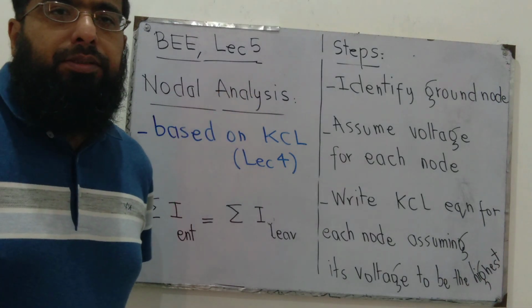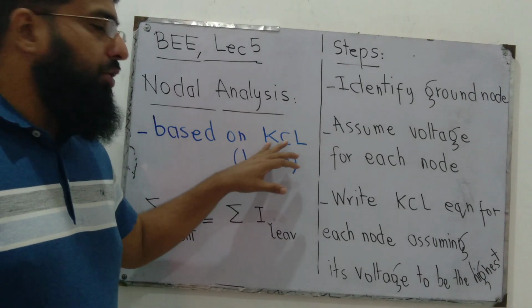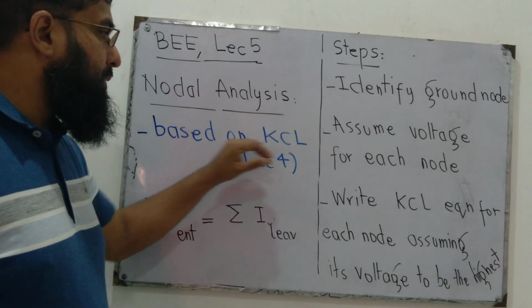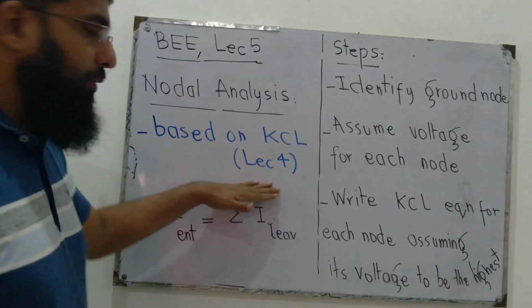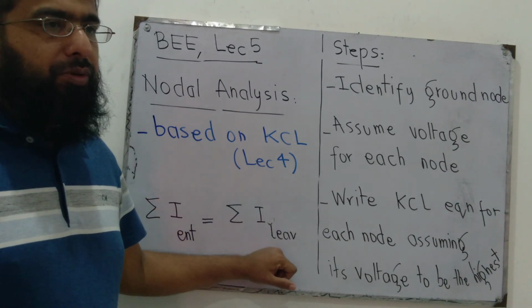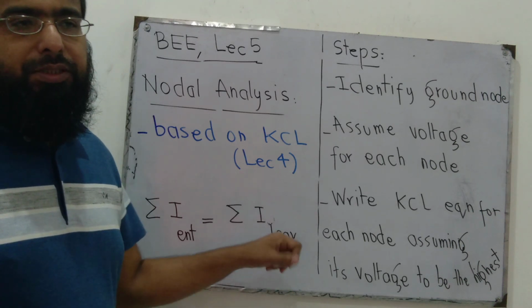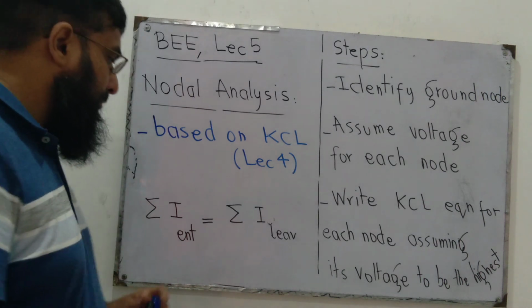Nodal analysis is based on the famous Kirchhoff's current law. We studied KCL in Lecture 4. It says that the sum of entering currents is equal to the sum of leaving currents from a node. A node is a point where branches meet and current divides.